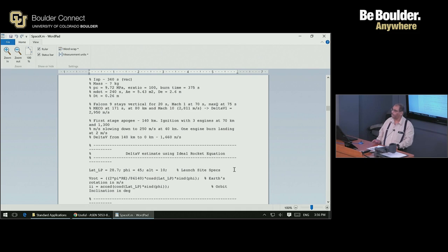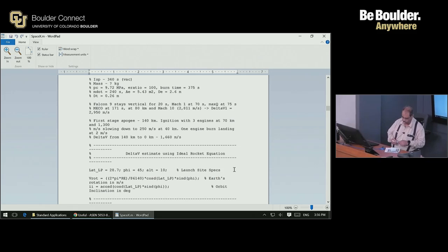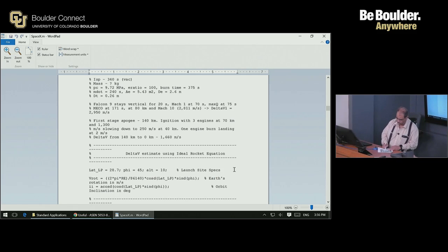But whatever data you use, as engineers, we need to run them through a sanity check. Does this make sense? If the thrust-to-weight ratio of a launch vehicle becomes less than 1, obviously there's something wrong with the data. Things like that. So apply a sanity check to your data. That's pretty much all that is about the homework.